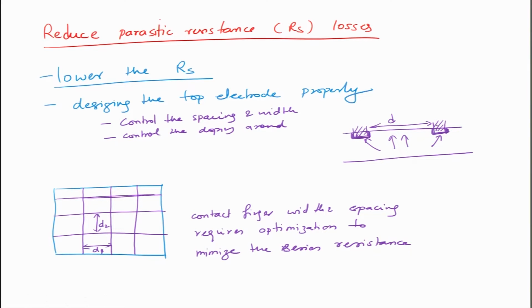So, the doping around the contact, as I said, there is a gradient in doping. It is not the same doping all throughout. So, basically you can say there is a gradient in dopant concentration around the contact. And generally these contacts are narrow on top, but they are buried, which means with high depth.